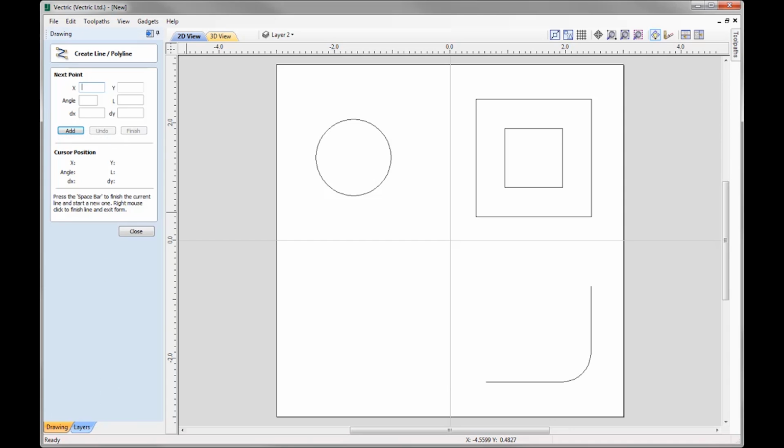So let's go into the Polyline tool. So let's bring the cursor into the job. Now at the moment we are currently not seeing any form of lines or extensions that I spoke about earlier, and that's because I've not yet clicked to create the actual polyline and I haven't woken up an object for me to align to. So what do I mean by waking up an object?